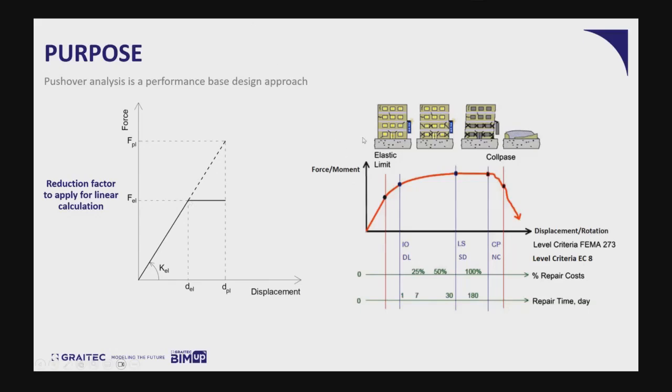So in the performance-based design, we are interested in how far we have plasticity in the structure. This depends, of course, on the type of the structure. If the structure needs to remain operational or to have little damage after the earthquake, if this is an important structure like a hospital, fire station, etc., in this case, we design to have little to no plastic deformations during earthquakes. So we have strict limitation that we can see over here, for example.